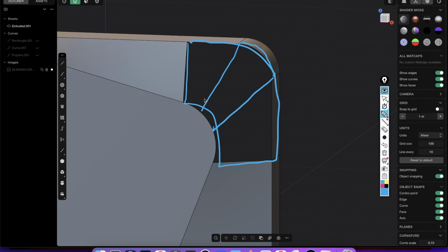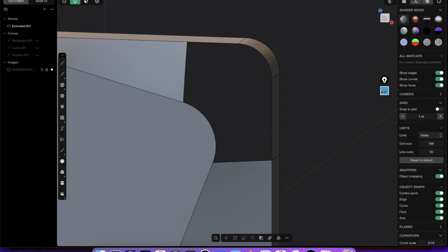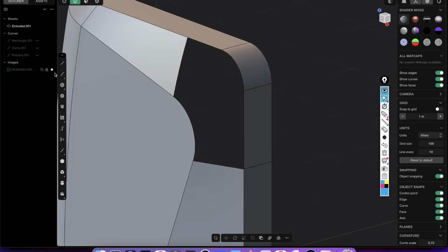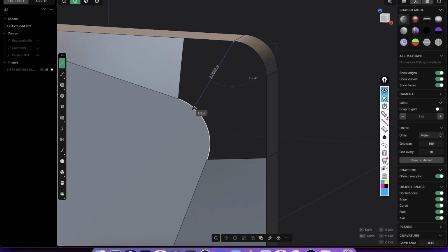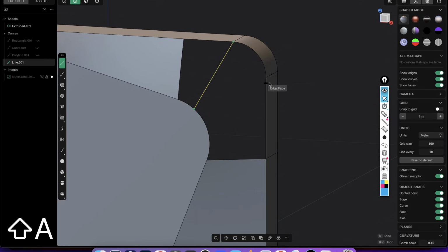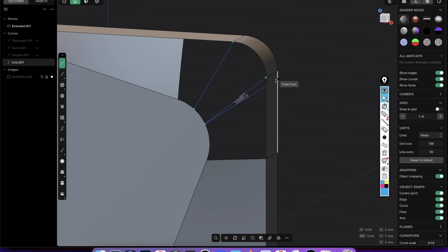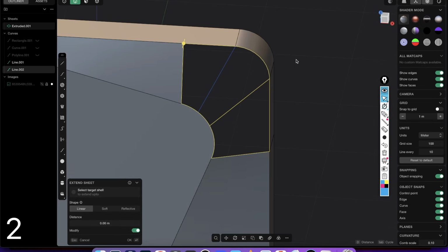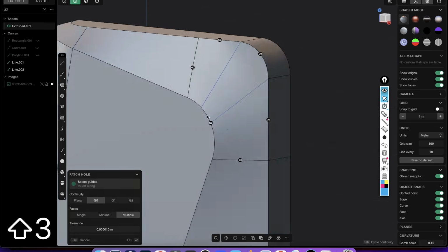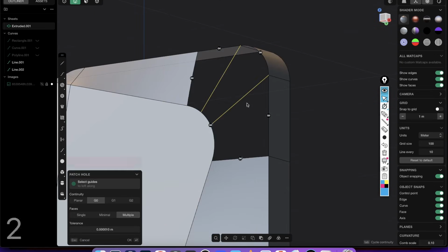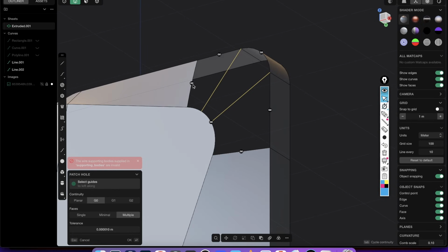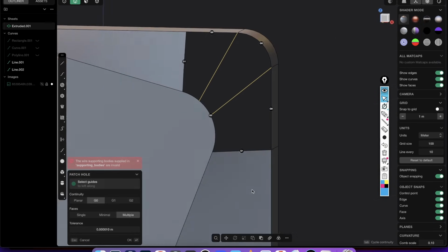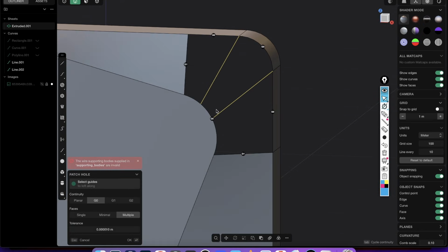squeeze them to our guiding lines or curves, which is very simple. So let's do that by creating a line, snap it here and snap it somewhere here. And again, Shift A, create a new line, snap a line somewhere here, right? So it's just very experimental right now. But now if you press 2 and again Alt click, you select this, first click it out. So again, select only this loop without those curves and patch it again. And now Shift click and Shift click these curves and it breaks because you have to give here G1 and here G1 and it does not work. Why not? Let me check.